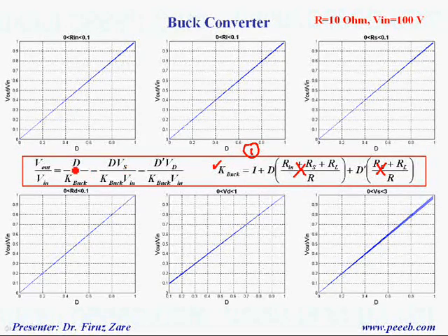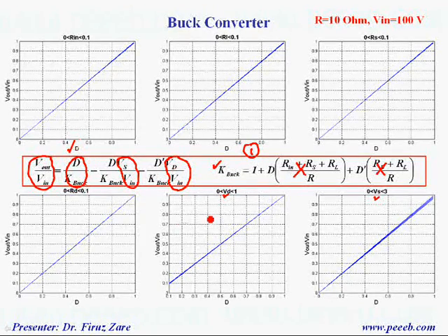So if you look at this equation, the conversion ratio, because K is almost equal to 1, we have this number, and now this factor is determined by Vs over Vin and also Vd over Vin. So here we can see if the Vin is much more than Vs or Vd, the voltage drop across the diode or the voltage drop across the switch, the conversion ratio is almost the same as the ideal component.